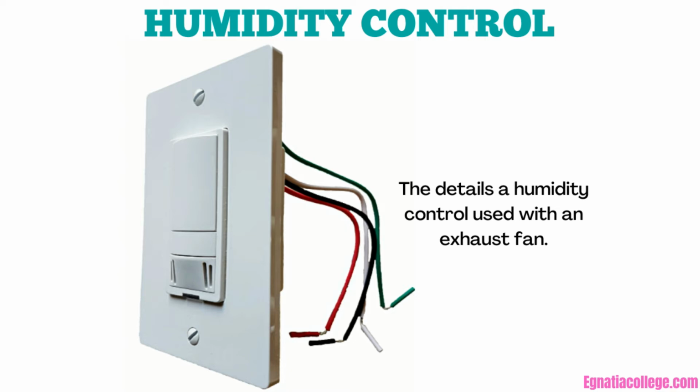In addition, the framing members, wall panels, and plaster or drywall of a dwelling may deteriorate because of the humidity. Insulation must be kept dry, or its efficiency decreases. A low humidity level can be maintained by automatically controlling the exhaust fan. One type of automatic control is the humidistat. This device starts the exhaust fan when the relative humidity reaches a high level. The fan exhausts air until the relative humidity drops to a comfortable level.